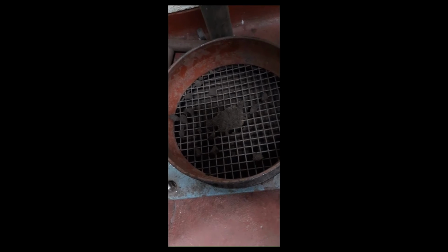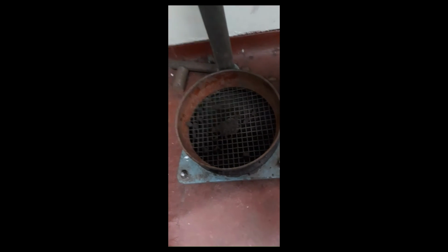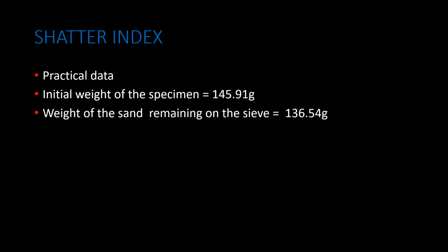Then we collect the sand remaining on the sieve and weigh it. Here you can see the initial weight of the standard specimen and the weight of the sand remaining on the sieve. Using this data, you can calculate the shatter index of the sand sample.